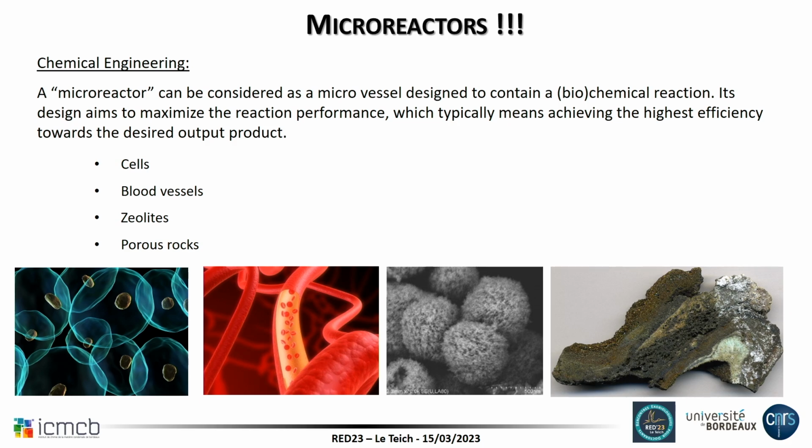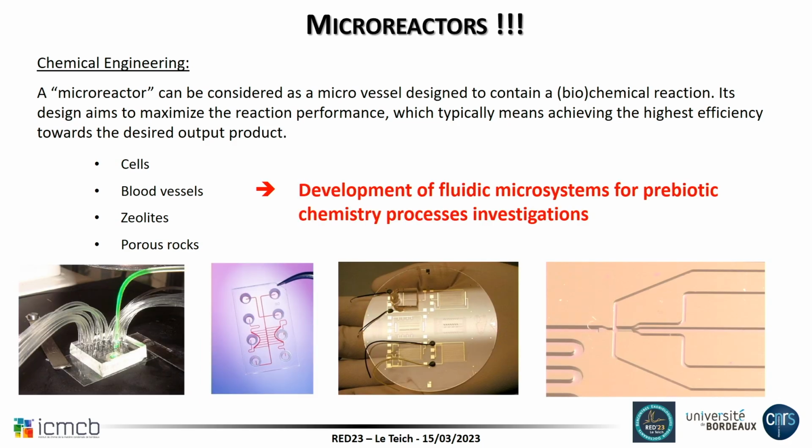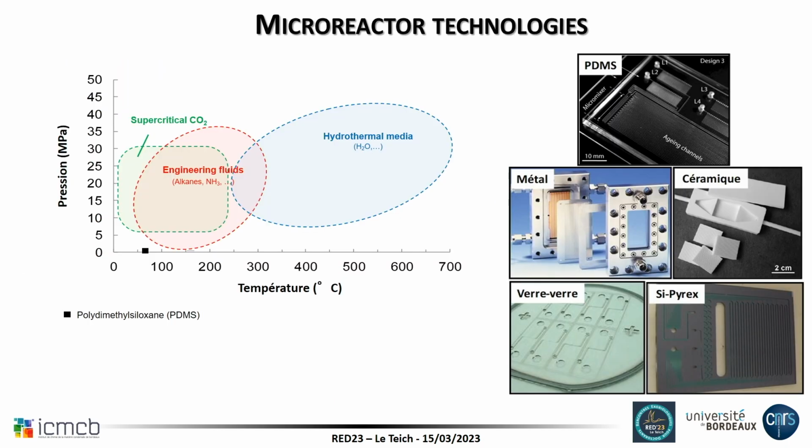So microreactor, you've seen this slide before. I showed you that those are membrane compartmentalized, those are confined environment. So let's do this type of things, but in real, with microfluidics. Microfluidics is the flow of tiny quantity of liquid in microchannel. You can make them the way you want because you can design them the way you want, and you can also create porous media inside a microreactor and place this under the microscope to monitor in real time and in real condition your chemical reaction.